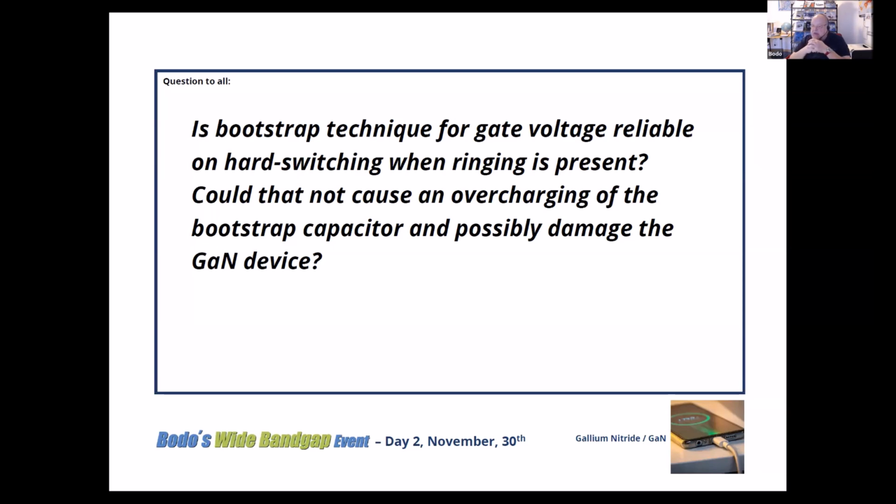Is the bootstrap technique for gate voltage reliable on hard switching when ringing is present? Could that not cause an overcharging of the bootstrap capacitor and possibly damage the GaN device?